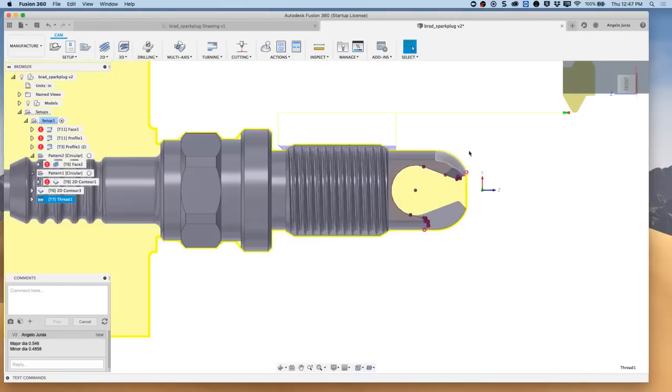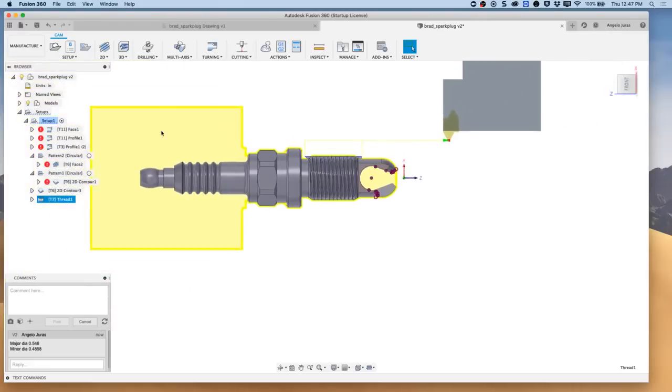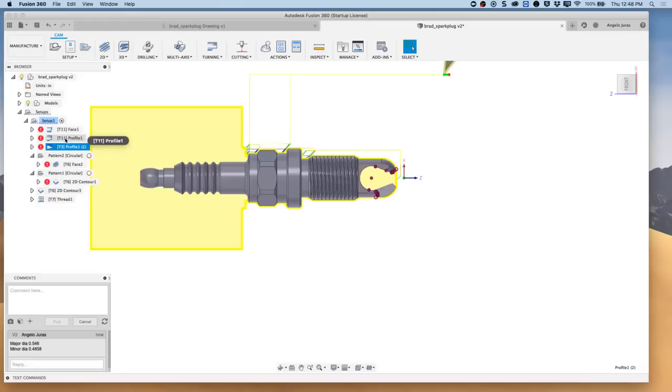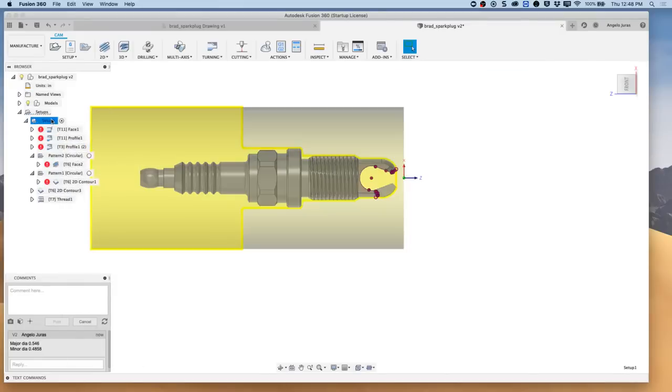I got everything machined thus far up to this point. So what I need to do next is machine the rest of the part all the way here. If you remember, I already machined it using these parameters with this step over and the stock to leave, and then I finished it with that. So what I'm going to do is copy those two. I'm going to go here, hit copy. Let's do it one at a time, and I'll paste it.